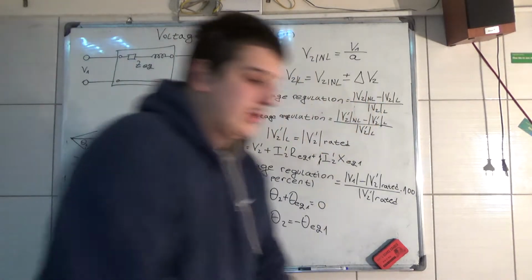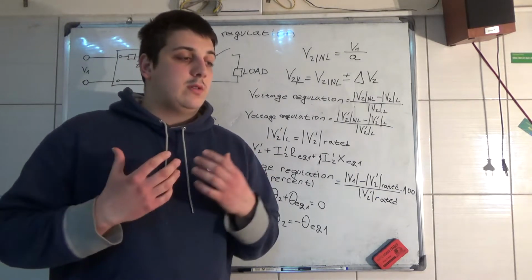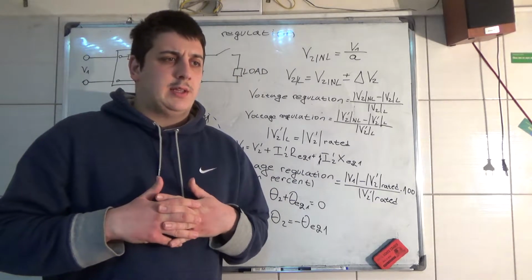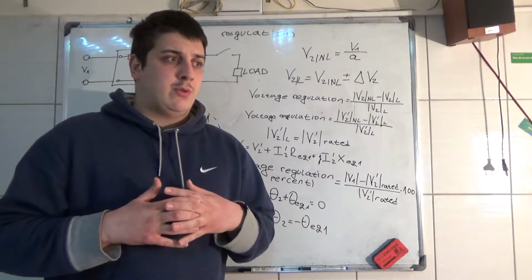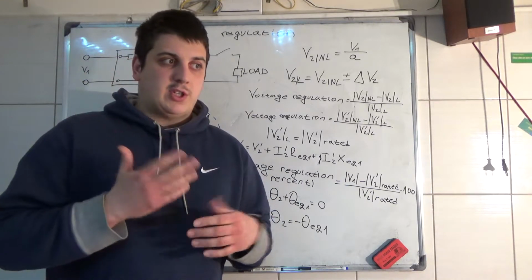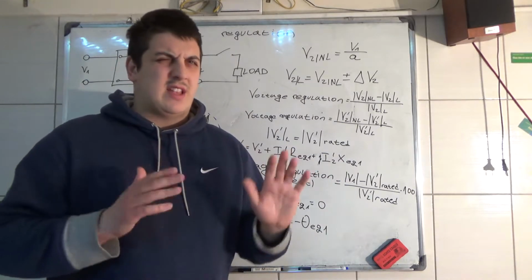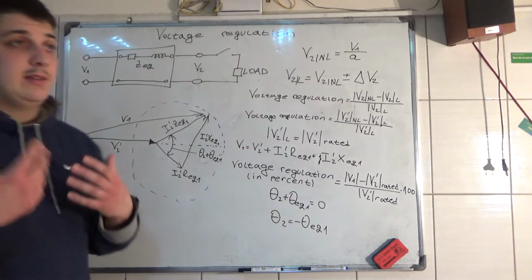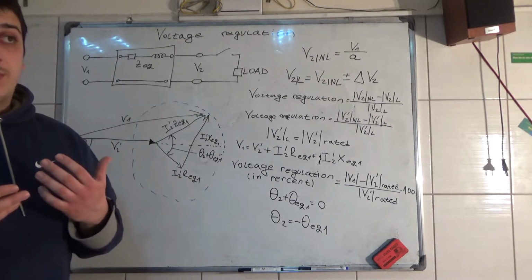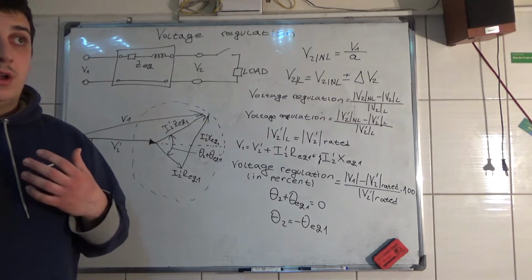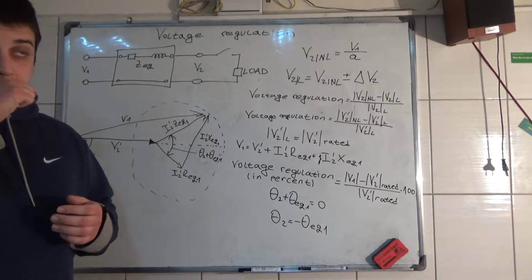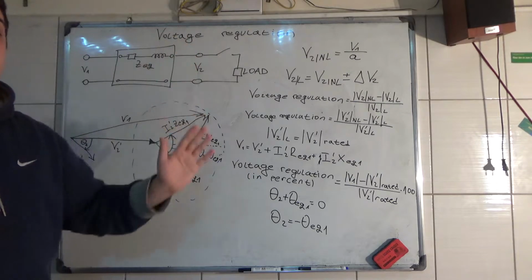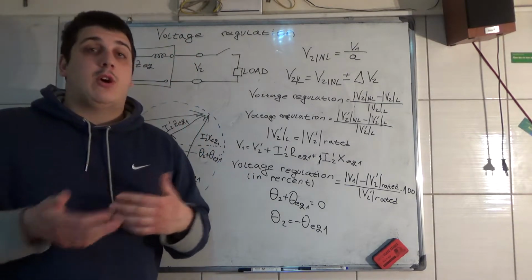So if you want to have, I don't know, 110 or 120 volts, I forgot what the distribution voltage is in America, I think it's 120 or 110, you have to make a smaller internal impedance of the transformer, because the more current is drawn from the transformer, the terminal voltage can vary up and down depending on the nature of the load.